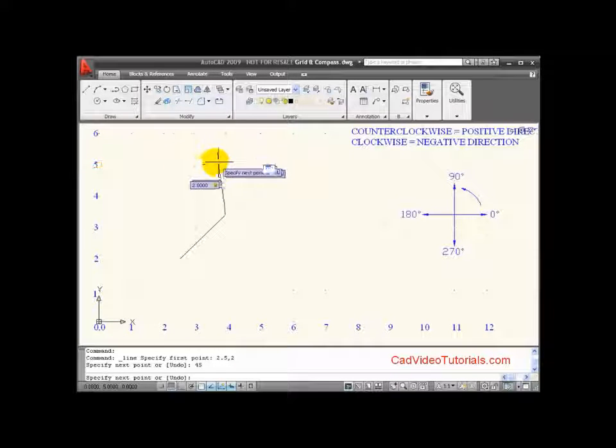Now the other key that I'm going to use when I'm using dynamic input is my down arrow key. And right now when I hit down arrow, you'll notice that I get an option of undo. If I hit the down arrow key again, the little black dot shows up next to the undo option, and if I hit enter, it will execute that option and undo that last line. To escape out of my options, I hit the escape key and it turns that off.